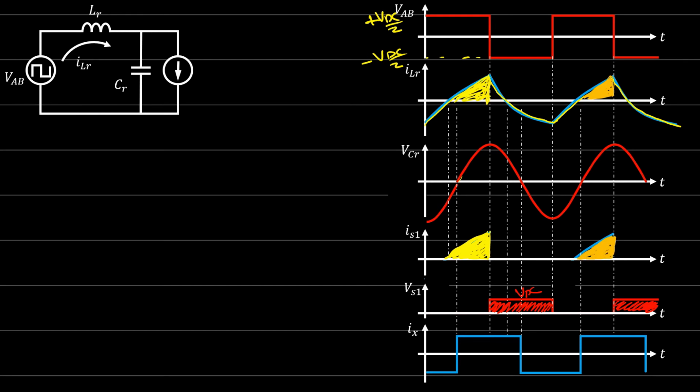Here we find that we have hard switching, and here we have soft switching, because switch 1 is on, switch 2 is on, and so on. When switch 1 is turned on, there is no current, so we expect no losses. When switch 1 turns off, we expect a current within the switch, so we have hard switching, and we have a problem here.